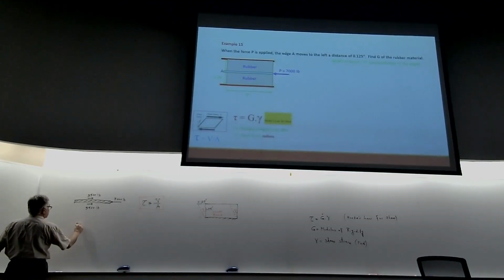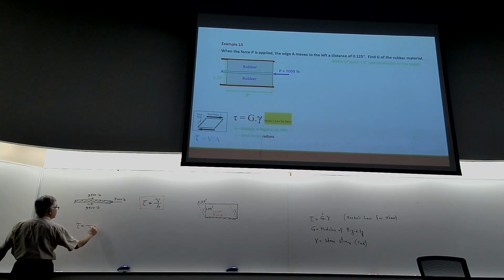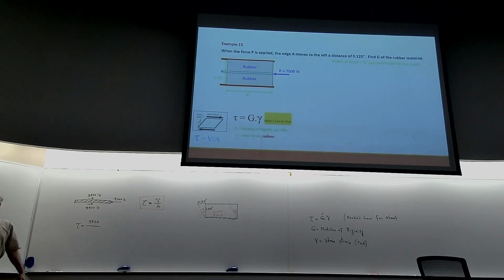And shear stress is V over A. What area would you use? The 9 inches and the 3 inches. 9 by 3, right?